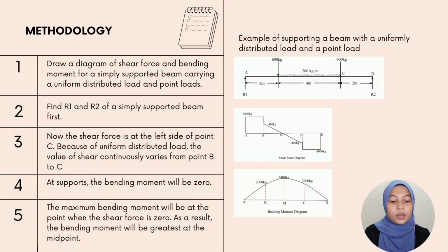Shear force steadily decreased at point C due to point load. Shear force is constant from point C to point D since no other point load is acting in this range.